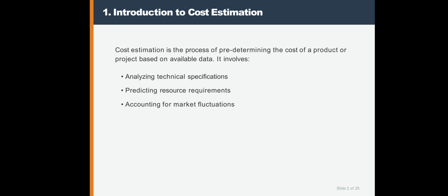Cost estimating requires high technical knowledge about manufacturing methods, operation times, etc. As I mentioned earlier, design time, amount and cost of materials required, production time required, labor charges, cost of machinery, overheads and other expenses are the different factors for calculating the probable cost of the product.